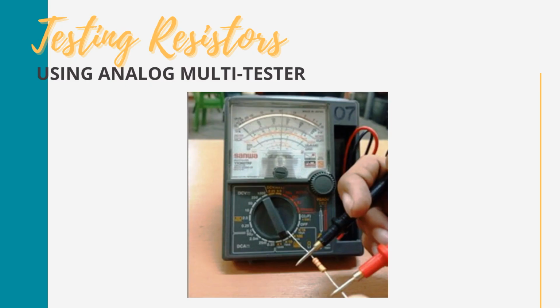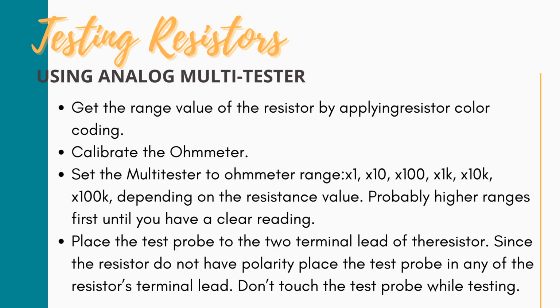Testing resistors using analog multitester. 1. Get the range value of the resistor by applying resistor color coding. 2. Calibrate the ohm meter. 3. Set the multitester to ohm meter range, x1, x10, x100, x1k, x10k, x100k, depending on the resistance value.